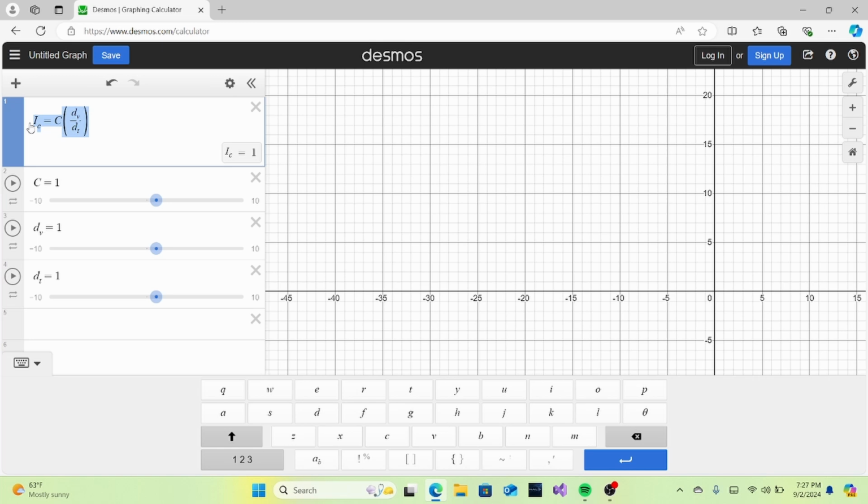It's just that as the voltage rises across the capacitor, it rises at a slower and slower rate, which means the capacitor current goes down. And with direct current, once the capacitor reaches its full charge, the voltage is no longer changing. Therefore, we get zero as our IC value. So there's no capacitor current whenever the capacitor is fully charged.